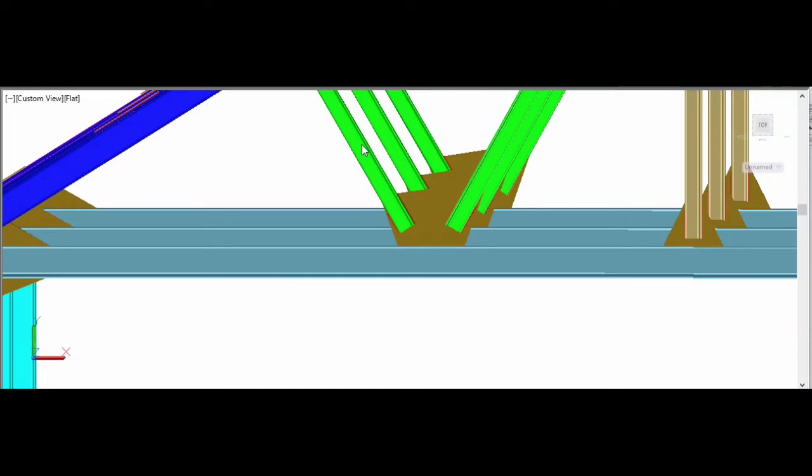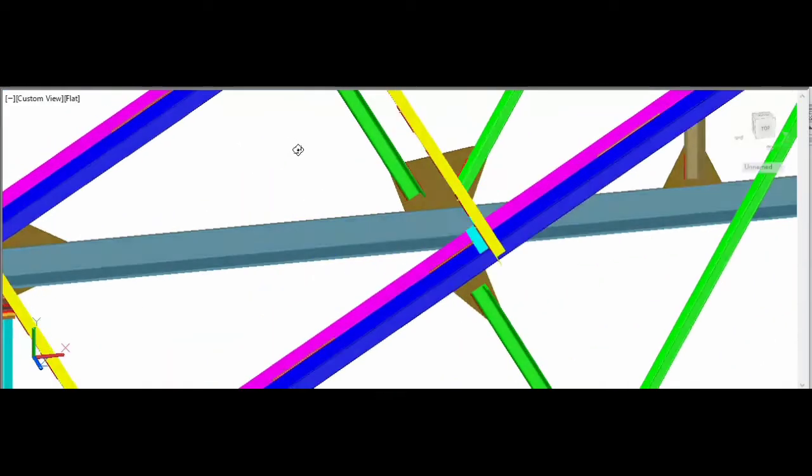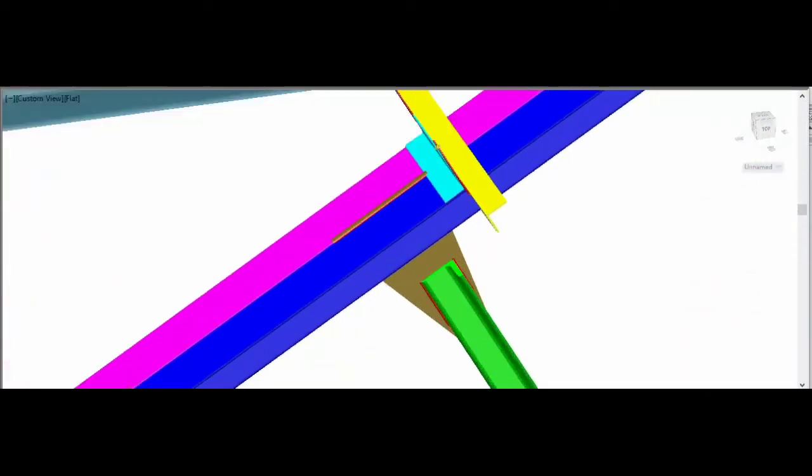In the case of double angle sections, either this connecting leg may be a smaller one or a bigger one. So we can connect the long legs back to back on either side of the gusset plate.